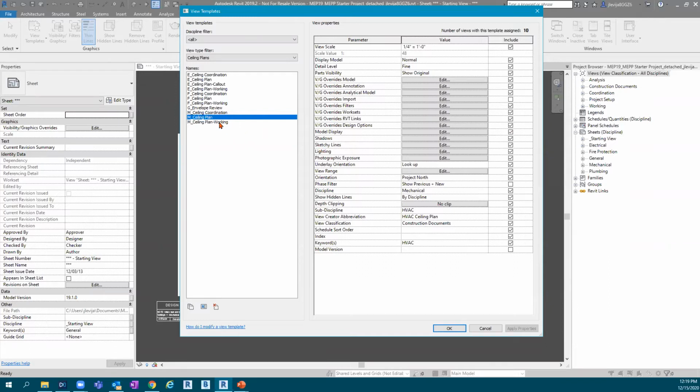But we have flexibility here, and I utilize this in both my design side of the industry as well as my VDC side, especially doing shop drawings. It's fairly quick to set this up and fairly quick to move stuff across. Make sure as well, on top of that, the project browser goes a long way. If you're working with these view templates, you'll definitely want to have the filters and the project browser whenever you're working with them.